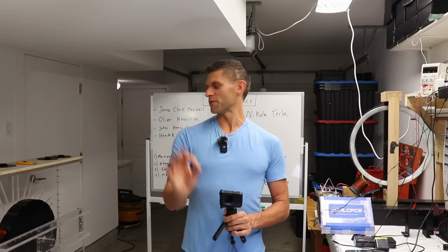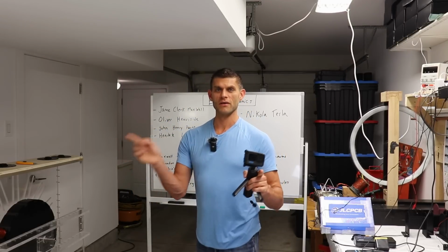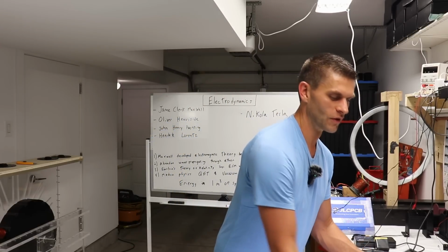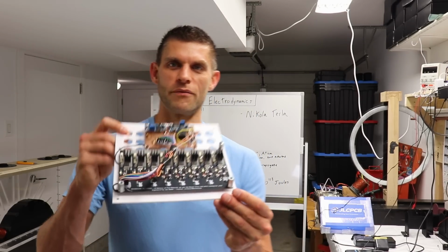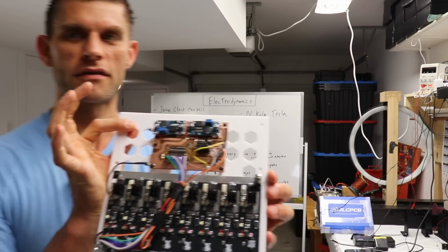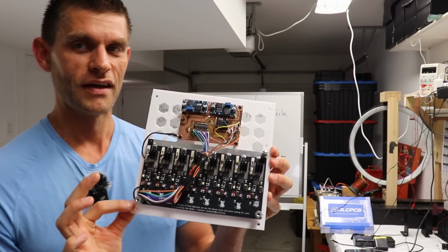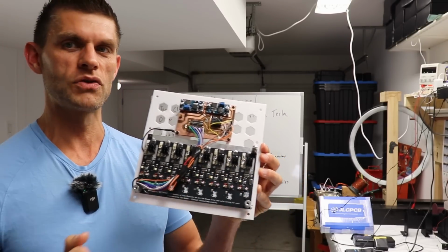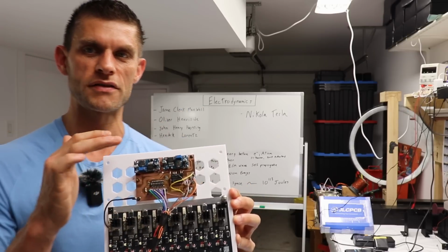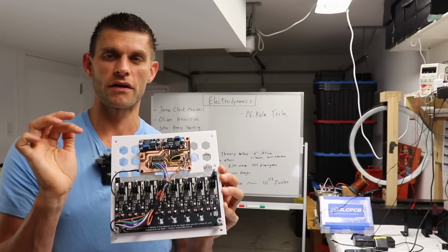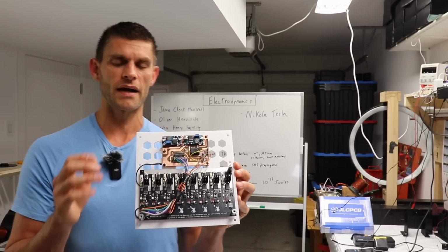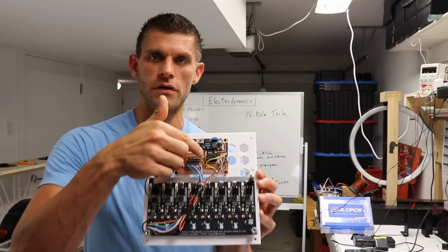Got into it a little bit deep there. Now, let's talk about the build and what we've been up to, you guys, because it's looking absolutely incredible. Joe has completed these first electronics, and this is our N-channel MOSFET board switching circuit. We've got 8 individual circuits here. These are the power supplies. So basically, you're stepping down. This particular one's going to operate at 36 volts max. So 36 volts goes into the top here.